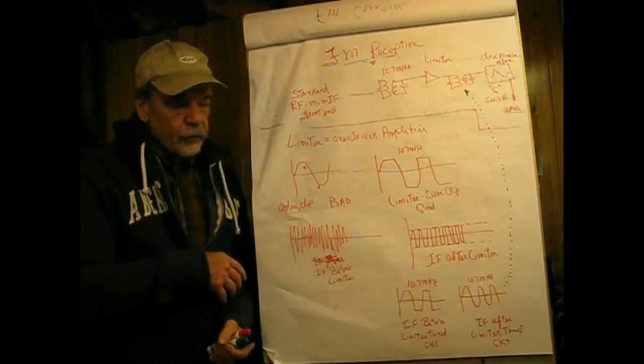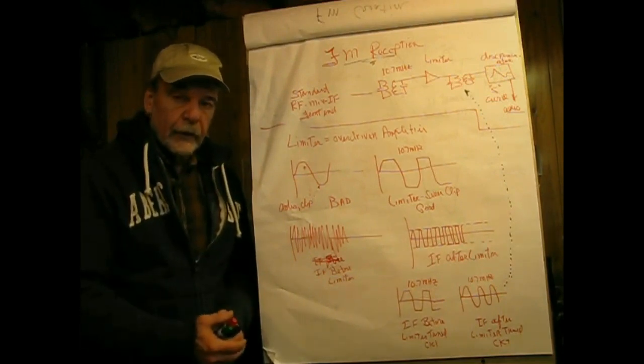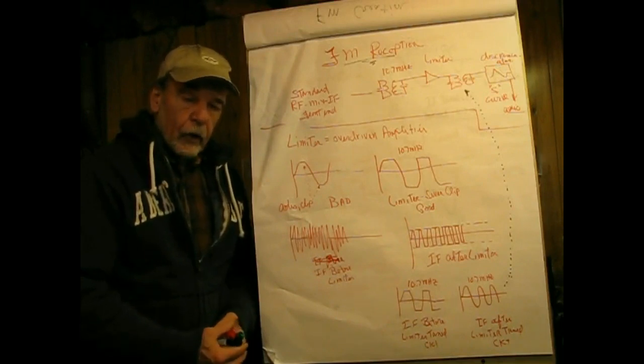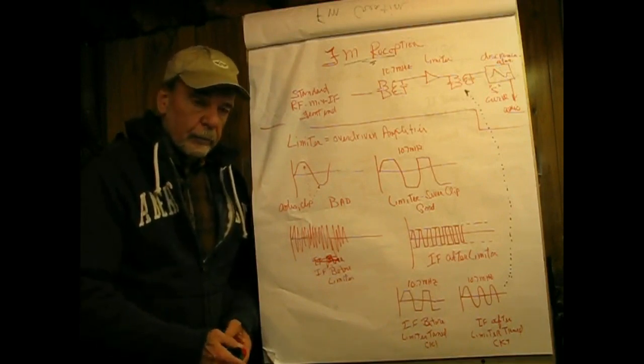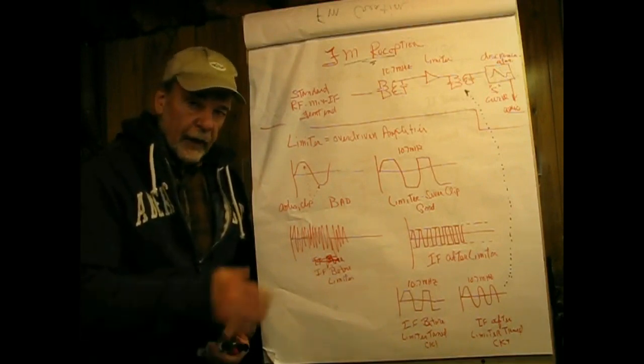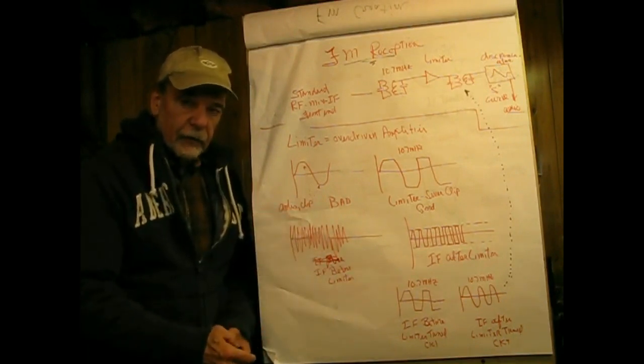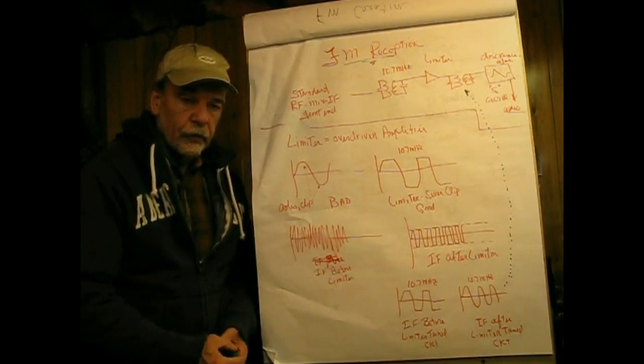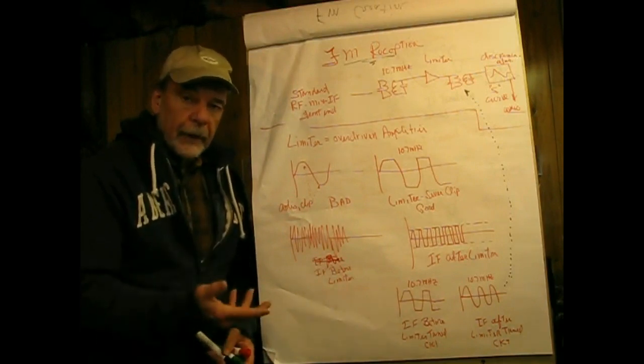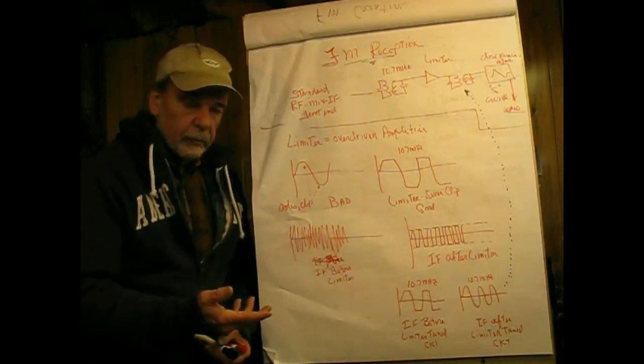So all it does is translate that signal, bringing it down to IF. It does not alter the sidebands, with the exception of high side injection reversing the upper and lower, but that's not of significance if we're not working with signals that are polarity dependent, and audio is not one of them.